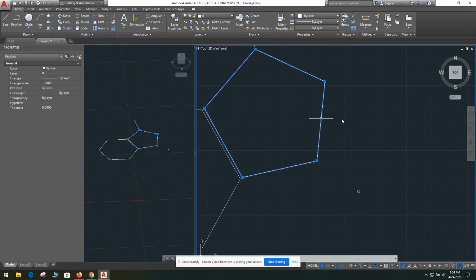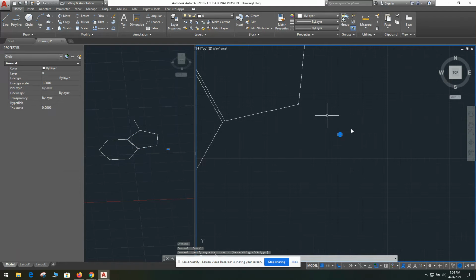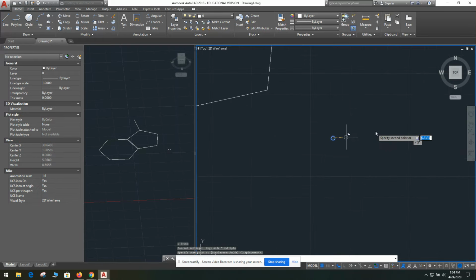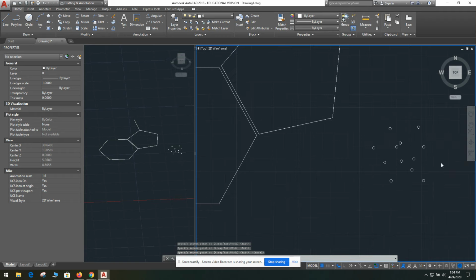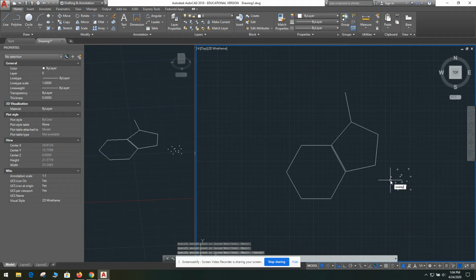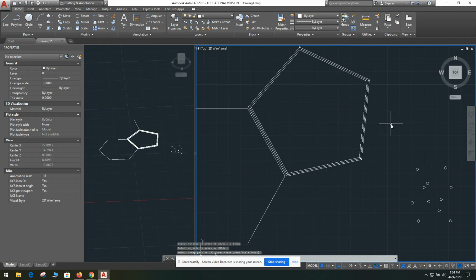So what I'm going to do is, I've already made my lines here. You're going to have to make your secondary lines prior to sweeping because you'll lose something from sweeping. Now remember, when you sweep, you lose the circle. So you're either going to need to make a bunch of copies of it, or you have to remember what the circle is. Either way, it gets used when you sweep. So if I sweep and I use this circle, enter, and then I use this as my path.